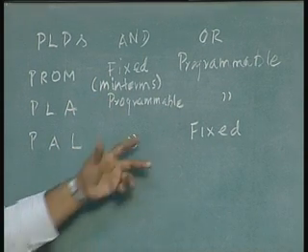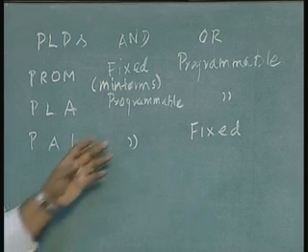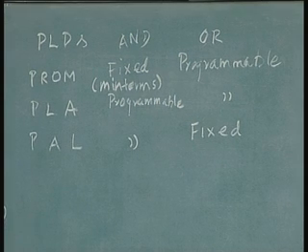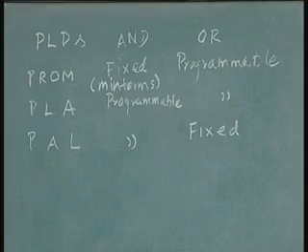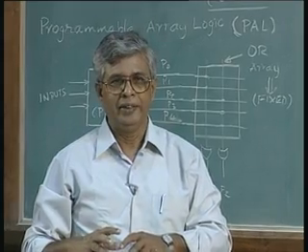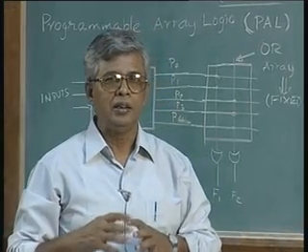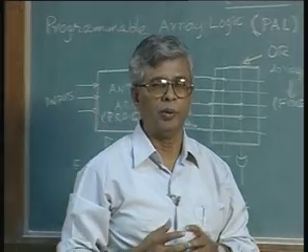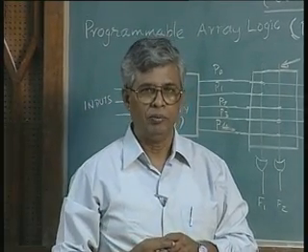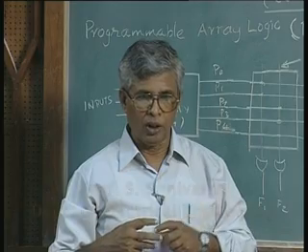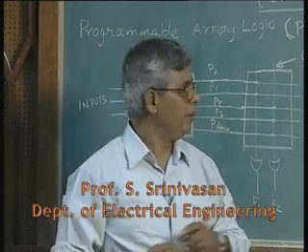Then we are going backward by one step, because in this case this is too much. 2 degrees of freedom is difficult to optimize. So, we have a programmable AND structure and a programmable OR structure. Most of these designs are automated, you should realize this. We take simple examples in the class so you understand it, but in practice the systems are huge, with a large number of inputs and outputs. So, when you design a tool to optimize, it becomes more efficient to optimize when the number of parameters we optimize is small. So, that is the main reason.